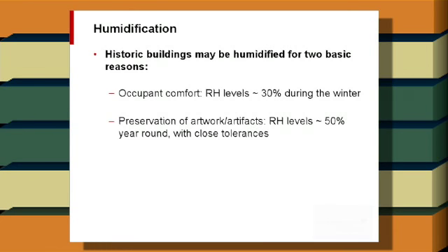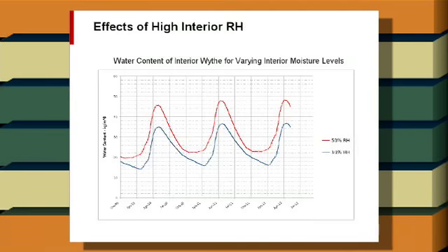And really the more typical driving factor to add humidity to a historic building is preservation of artwork and artifacts. Curators like to see 50% relative humidity with very close tolerances. And again, you can use some modeling tools to look at the water content of brick masonry at 30% relative humidity and 50% relative humidity, and not surprisingly, you get some uptake of moisture there.